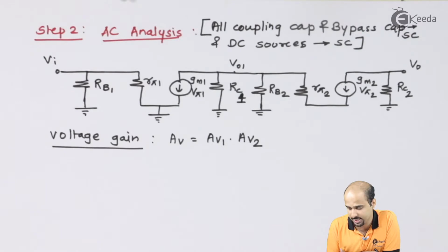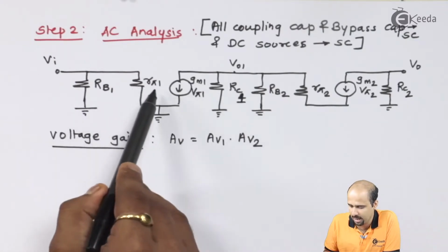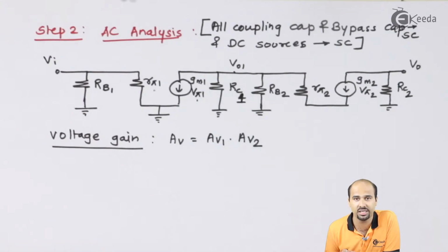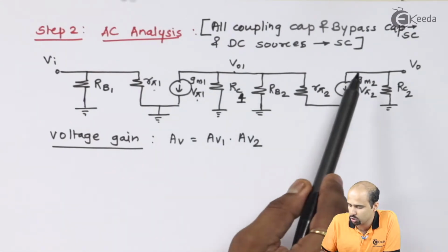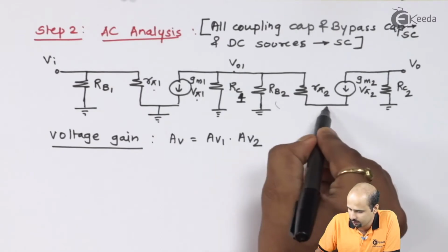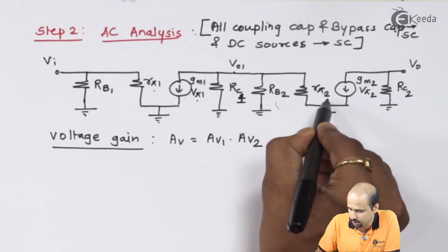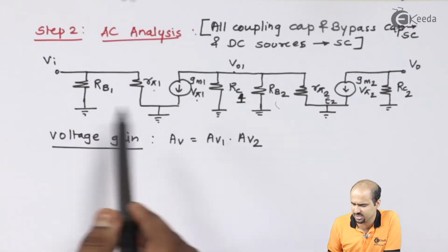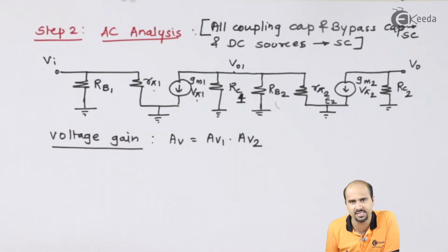This is how we will get the AC equivalent circuit, where R-Pi1, GM1, V-Pi1 is the connection for the BJT at the first stage. R-Pi2, GM2, V-Pi2, connected with ground at emitter 2, gives you the BJT AC equivalent for stage number 2, and the respective resistances I just have to place according to the given circuit.